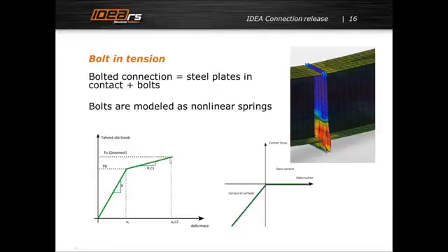So finally we invented this diagram where there is the initial elastic part, and then not a horizontal but this plastic branch, and this is derived from results of tests of bolts, because the bolt as it is cannot plastify, but things like, I don't know this English word, things like this nut and some parts are really plastic.